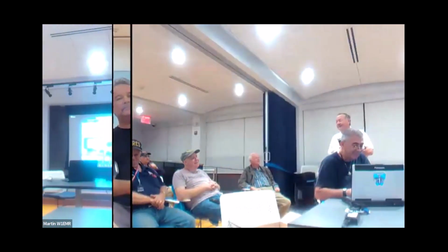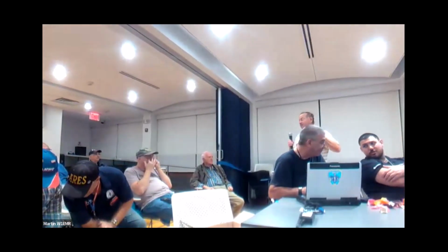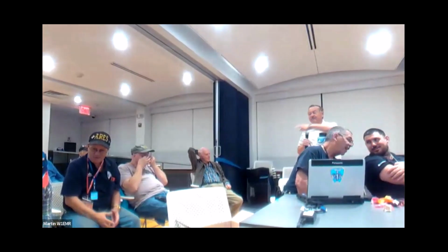Anyway, a lot of us have much more experience with A to D converters in cell phones and in stereo systems as opposed to ham radios. With ham radios, I have an ICOM 7300, and I know there's other people in this room that also have a 7300. That's an example of a hybrid one in which there is an analog mixer in front of the A to D converter, and the A to D converter in the 7300 radio works at an IF of 24 kilohertz.